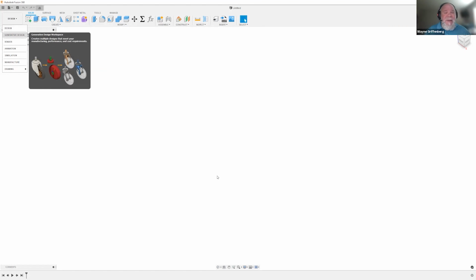We have a generative design workspace, a newly added capability where you can upload your design requirements. So if you're looking for ideas or want to iterate, let's say a custom fixture for multi-axis work holding, and you're thinking of a way to hold the part, but you might have some interference or some way that a standard fixture might not work, you can upload your design idea, your requirements, how you want to make it, the material you want to make it out of, and perhaps the process, whether it's going to be a cast part, 3D printed, or a hybrid of all that with machining.